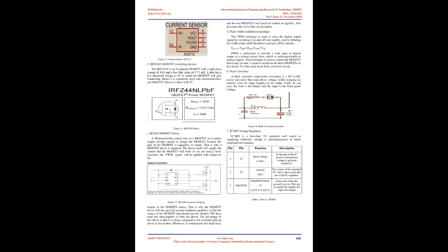Some PWM regulators have provisions for converting it into a series, on/off, regulator. This could be needed for sensitive loads, which have an issue with the noise created by the frequency of the PWM. Because PWM charge controllers require transistors, they are always solid state, this means heat dissipation can become a problem, especially in larger solar arrays. Figure 7. PWM controller current to battery for a given duty cycle.